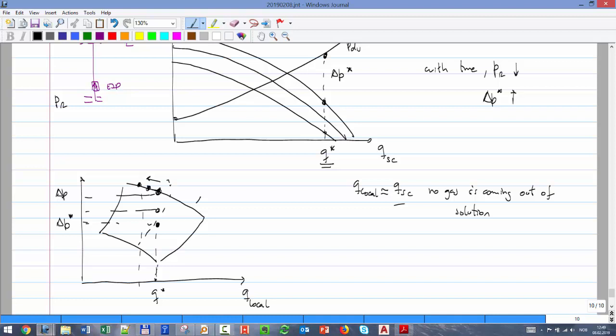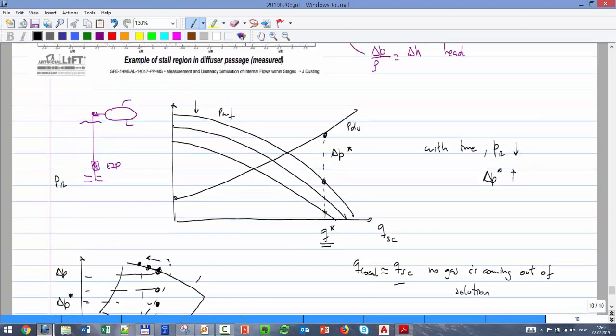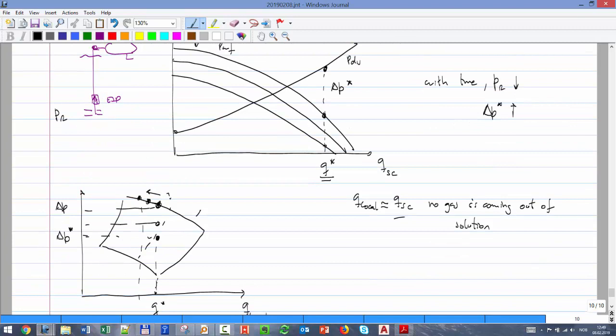And that's the exercise you're going to make. You have to calculate this Q and delta P versus time, and then see if you are inside the region. If you're not inside the region, you have to correct the rate. Basically that's how the process looks, going up and up and then going to the left. Of course, when you start to deviate, you get far away from the best efficiency line, and that's a challenge. Your pump will be less and less efficient.